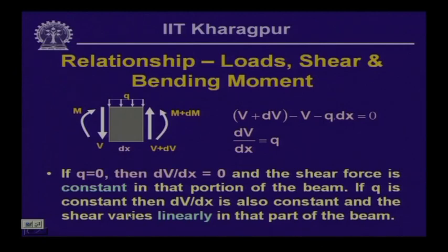Well, now, as I told you last time, the basic objective of this kind of analysis on beams, when a beam is subjected to transverse loads, is finally to evaluate what stress this particular member is undergoing because of such loading and what the deformation in the member is. To know precisely what the stress level is at any point and along the length of the beam, we need to know how these quantities, the stress resultants, the shear force, the axial force and the bending moment, vary at different cross sections along the length of the beam based on the loadings it is subjected to.